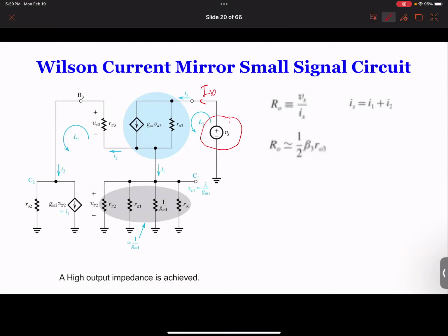Right? So then we use Vx over Ix. We got like the resistor RO. So you can apply a voltage source here. When you see this circuit, how many nodes does it have? This node over here, or this whole thing is one node. Even though there's a line in between, they're actually one node. And there's one node over here. So they're basically two nodes.